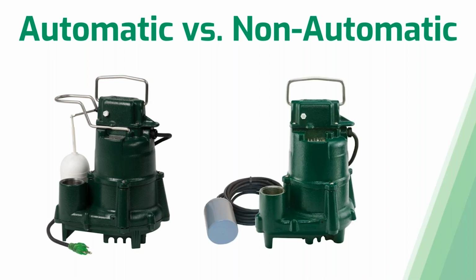Then you have non-automatic pumps. Non-automatic pumps do not come with an attached float switch. You're typically going to need some type of external start component, be it a piggyback float switch or separate float switches with a control panel. Non-automatic pumps are typically used in all sorts of different applications, and they typically fit a wider range of applications as well.